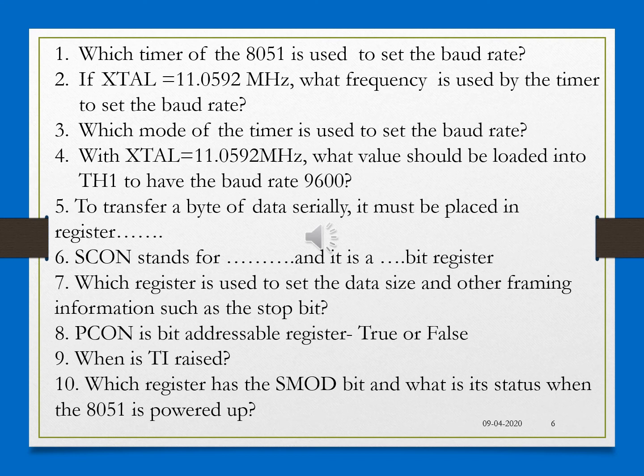So how do you calculate that? So 28,800 hertz, you divide by the baud rate required, that is 9600. So what you get will be 3. So that is the value, -3 in decimal and FD in hexadecimal. So that value you will be loading into TH1 register, right?